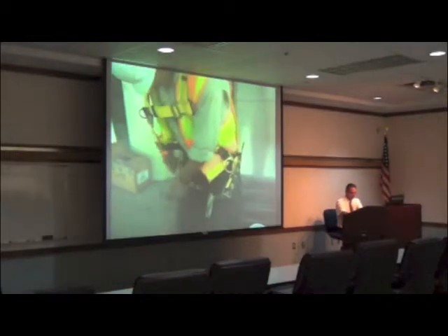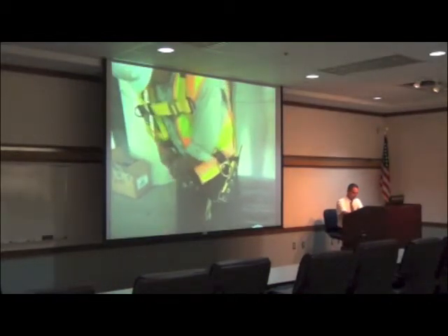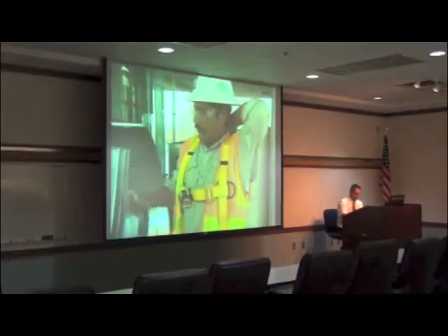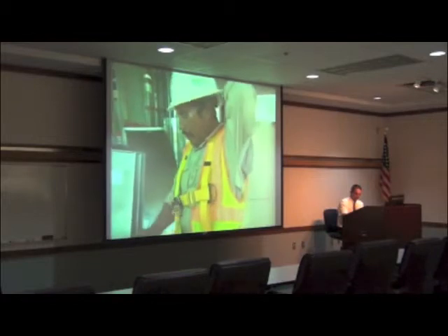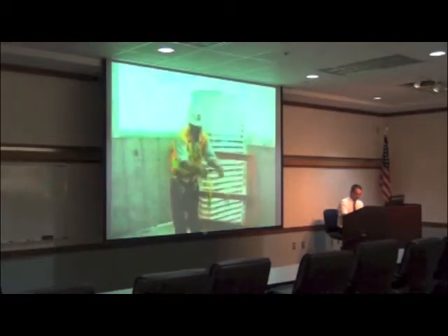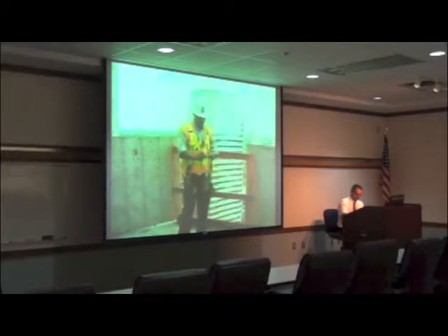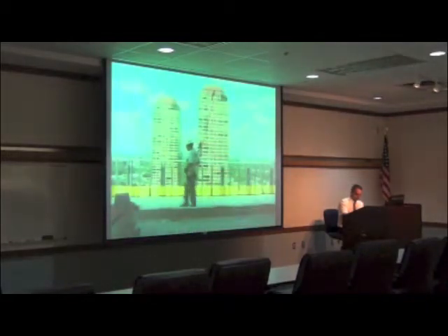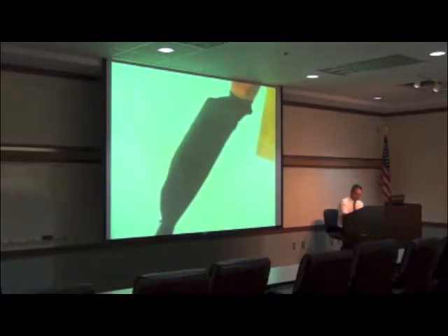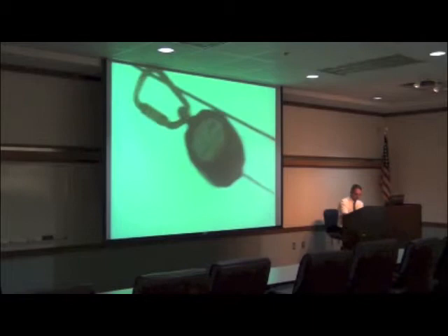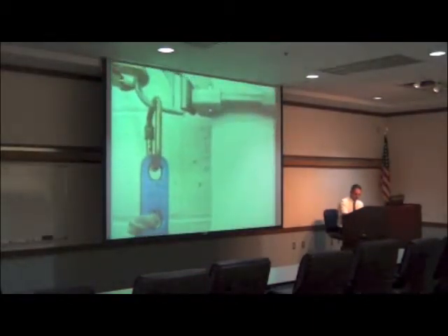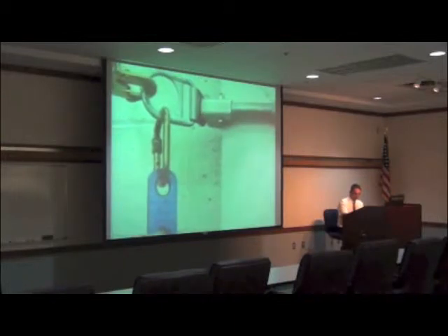If worn correctly, a personal fall arrest system can save a worker's life. If worn incorrectly, it can cause additional harm to the worker, possibly causing grave injury. A personal fall arrest system consists of a full body harness designed specifically according to the workplace application, a shock-absorbing lanyard or self-retracting lifeline designed to take the strain out of the fall, and an anchor, a secure point of attachment for lifelines, lanyards, or deceleration devices.